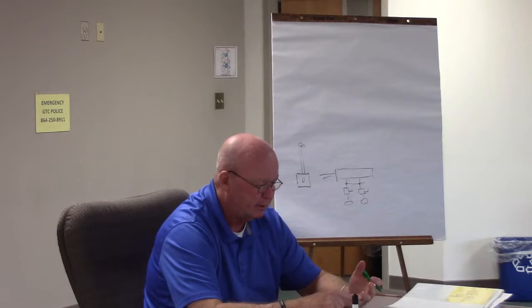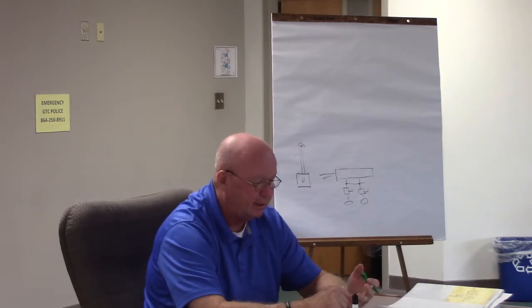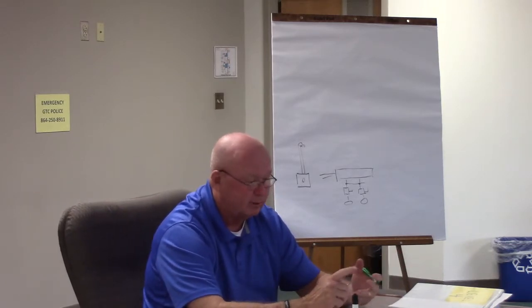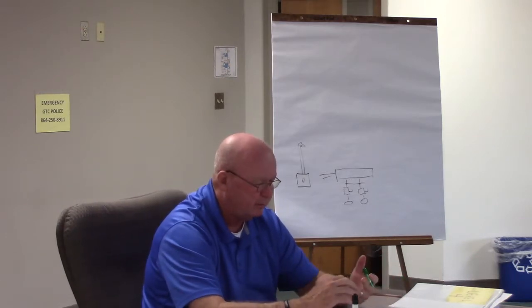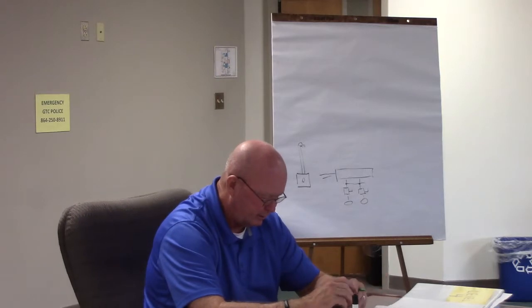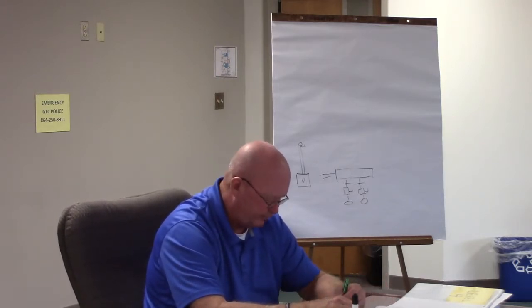And we'll get into what continuous loads are. Motors, for the most part, are continuous loads unless it tells you not. Commercial facilities where lights are going to be on all day, because what, 3 hours is continuous duty. So signs, a lot of things like that are considered continuous duty. Okay. All right.